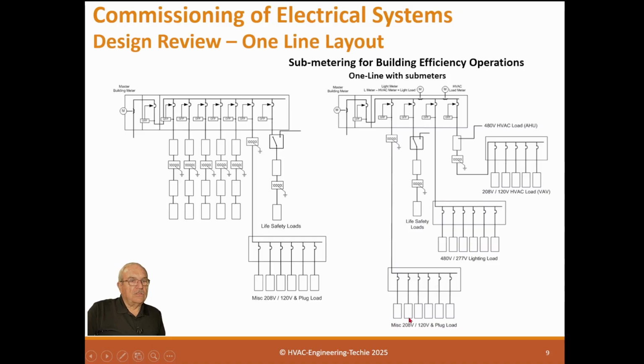So you'll notice this is actually a plug load. This is lighting load. This is emergency life safety special loads. And this is HVAC loads. Now, HVAC loads, it has a high voltage panel here that can take care of it, or it might, if it's a big job, might have a full distribution system for the high voltage, the 480 volt. And it might have another distribution for 208 down here at 120. But irregardless, we need it.